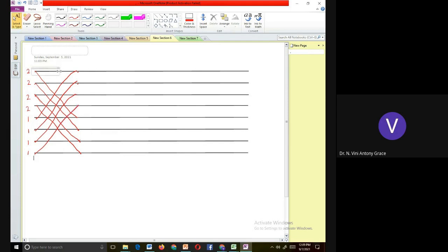For all the 4 lines in the lower half, you have to mention -1 within the butterfly structure. The procedure remains the same. -1 here, -1, -1, -1. Outside the butterfly structure, you have to mention the phase factor. It is 1 by root 2 minus j by root 2, this is minus j, and this is minus 1 by root 2 minus j by root 2. Hope this is clear. Now find the output of this.